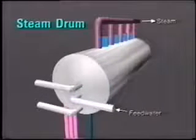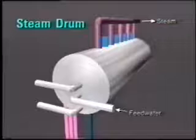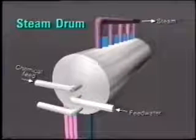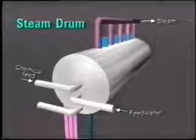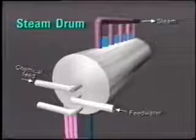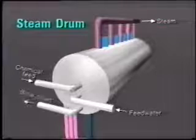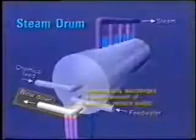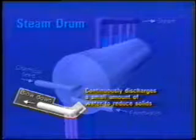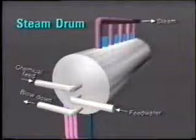There are various other piping connections into and out of the drum. A chemical feed connection allows us to inject certain chemicals from time to time as part of the boiler water control. Also, as part of boiler water control, a blowdown connection is fitted. This allows us to continuously discharge a small amount of water from the boiler drum in order to reduce solids. Both of these items will be discussed later in this tape.